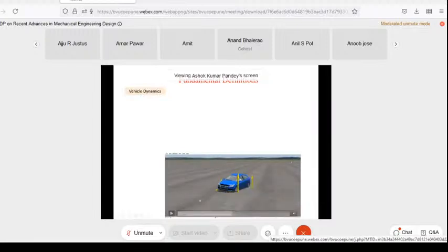Yes. So here you see that we have this force which is generated over here. What is this force? This is the force which we call the longitudinal force, which is along the tire. We also call it the tractive force. And then you also see there is a force which comes in this direction, that is called the lateral force.